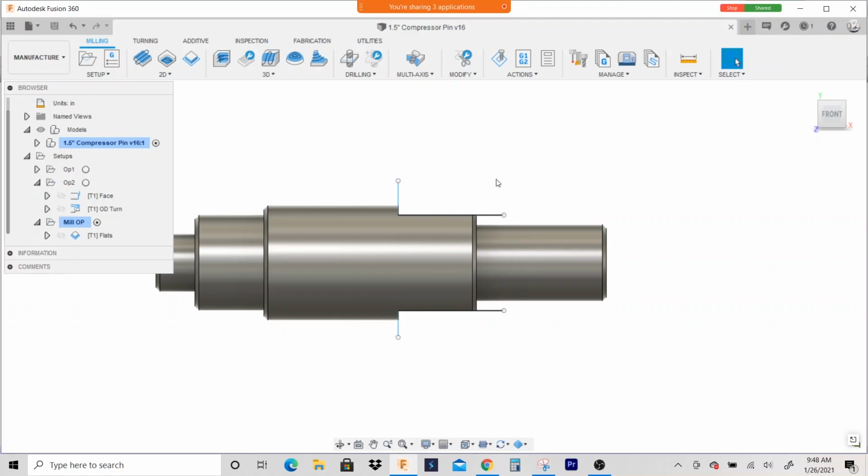You'll be turning the handle and feeding into the part, and then all of a sudden, once that force starts pulling on the workpiece, it'll pull the part down. Basically you'll start seeing the handle move by itself. If you're going at high RPM or a really high feed rate, the part can get away from you and you could junk a part, or it could turn into a dangerous scenario.